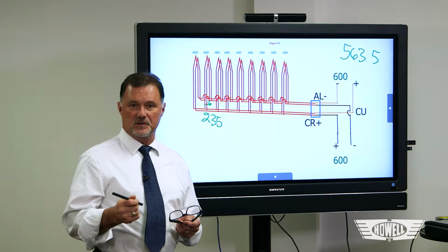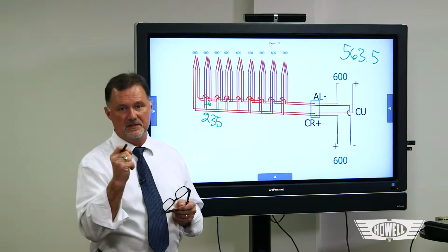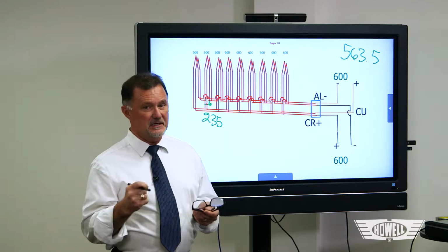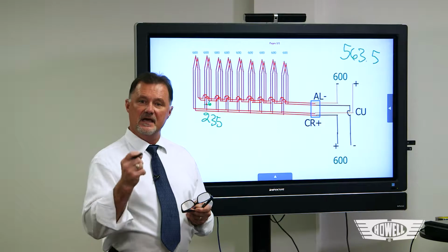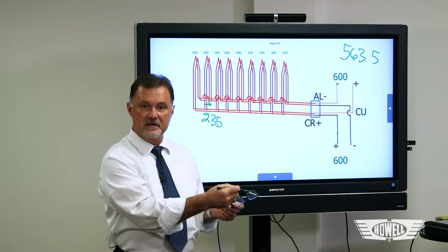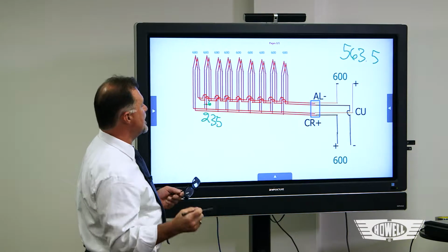Now, as I mentioned before, some of the impacts on the thermocouple averaging: well, you could also have a short. So inside the actual thermocouple housing, there could be a new junction based on the 2 wires touching the actual shroud. We can simulate very easily, and it's also a real-world malfunction, and that is the terminals, the chromel and alumel terminals on the apparatus or on the engine can become shorted together. So let me show you mathematically what should happen.